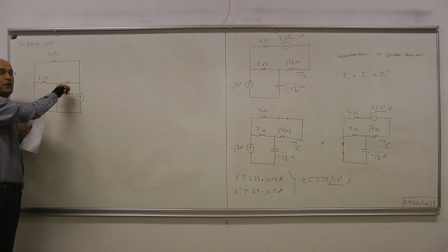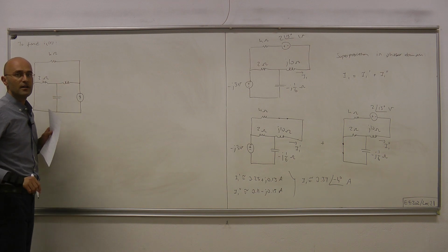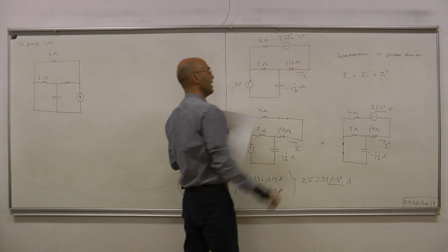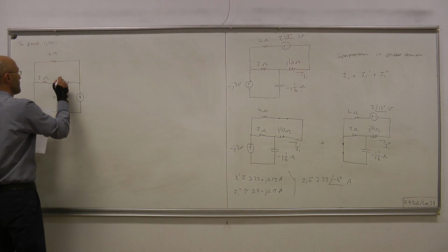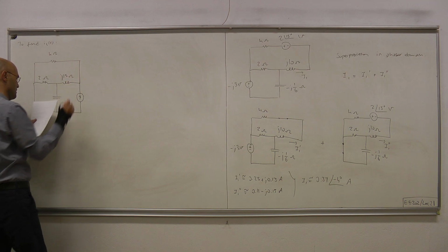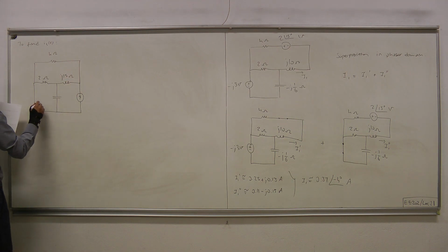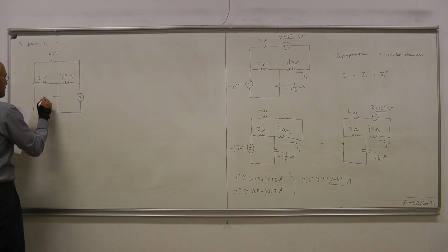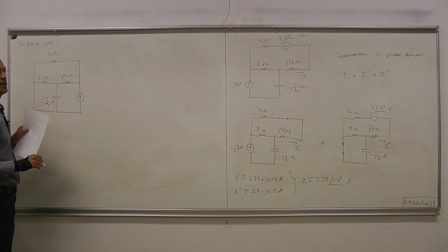So that means we're going to have different impedances for the inductor and the capacitor, different from J10 and minus J1/6. In fact, what we have is J omega L, which is J15 ohms, and 1/J omega C, which makes minus J1/9 ohms for this capacitor.